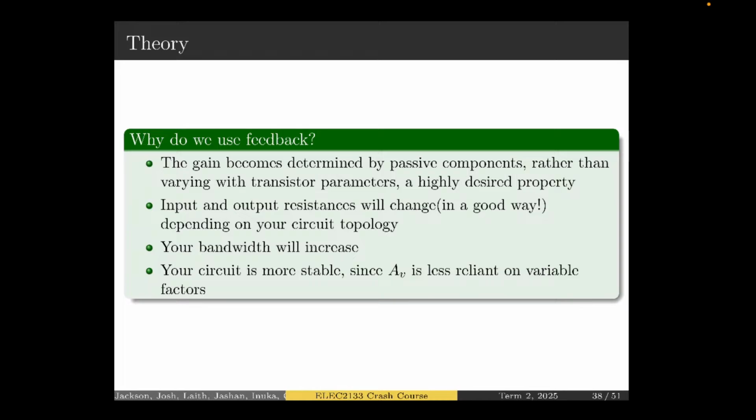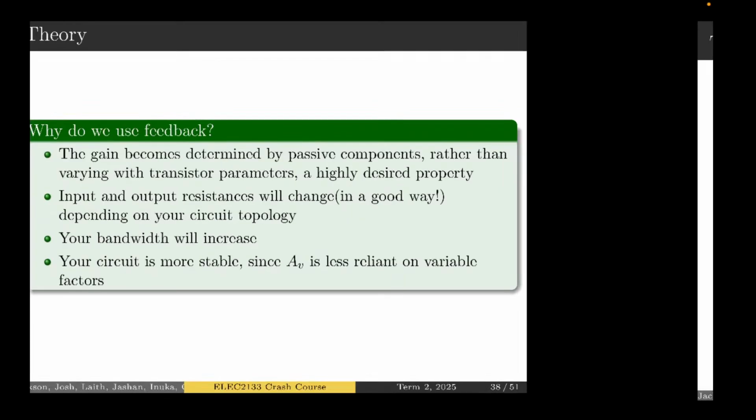One example is the temperature example. IS is determined by thermal voltage, like the equation we saw over there, and that first term, IS, is also dependent on temperature as well. If our supply rails change as well, let's say, because we're not going to use the lab bench power supplies for all our circuits, we can use a battery. And if the voltage changed slightly on that, your parameters would also change. And feedback fixes that. Okay?